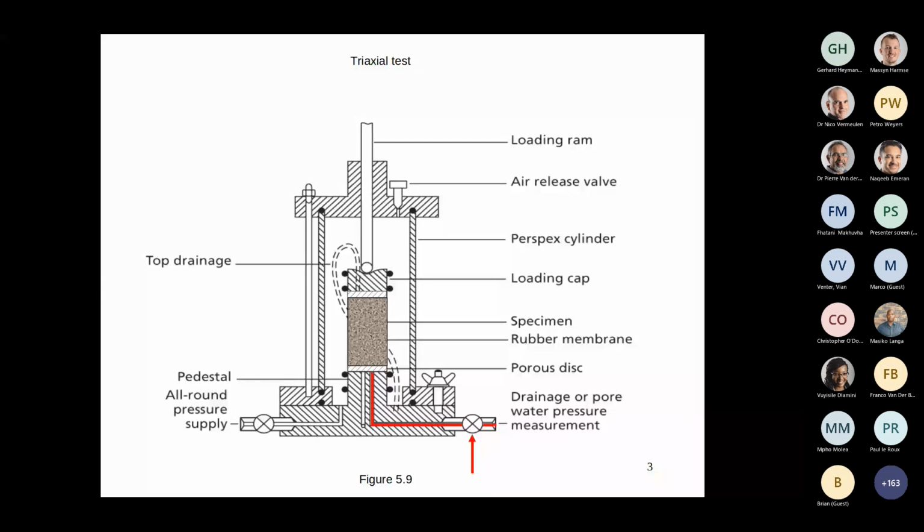Now, the unconsolidated undrained test is not commonly done in South Africa because our geology simply doesn't allow for that. Because you have to have a clay, it must be from below the water table. And if those conditions don't hold, we can't do the test.